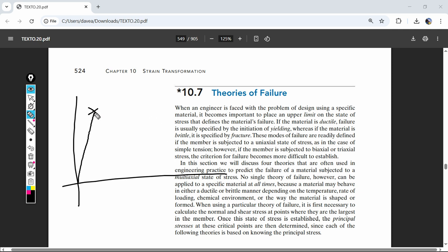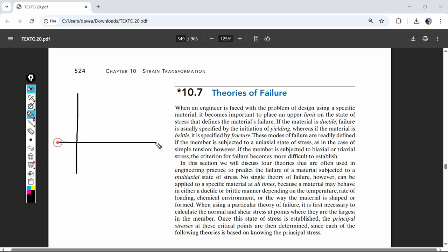Steel is going to yield for a little bit, then increase in strength, then decrease in strength, and then break. They're going to talk about how steel yields, and you wouldn't want to get into that yielding range. Brittle materials will just go straight up and then break; they won't have any elasticity. Every material is going to do something different, but this linear range is going to be the same, and that linear range is where we get all of our strength.